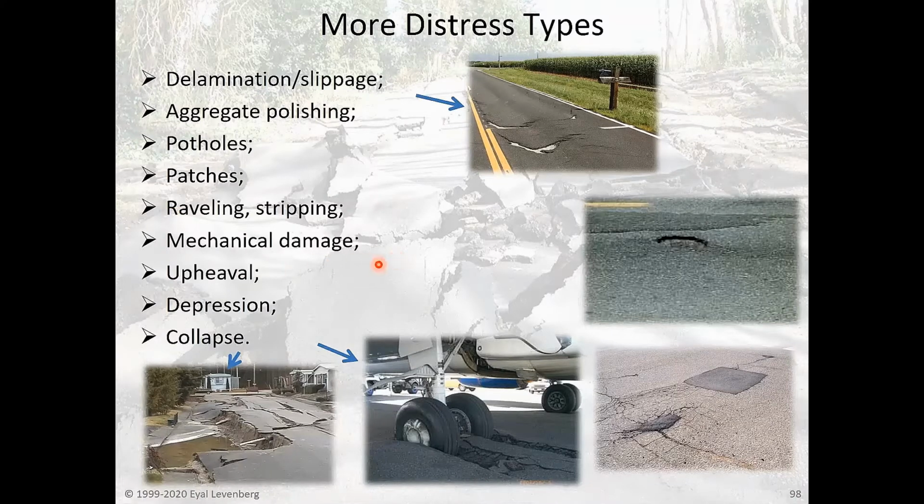Now, mechanical damage is where there's something falling on the asphalt and leaving marks. Let's say you have a crane and it lowers its supports and they dig into the asphalt, then they leave some impression. This is called mechanical damage. Another option is if something falls from a truck and is dragged behind, then you have mechanical damage at the surface. Others here, you can see their names.